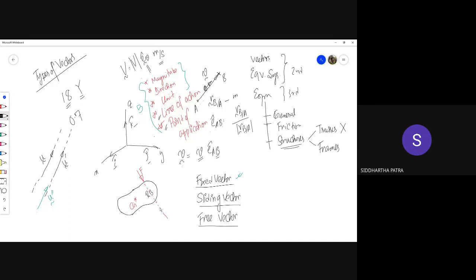So there would be an angular acceleration. So both linear and angular acceleration, and that would happen on the rigid body in the same way, instead of the force being applied on the line of action on the left side, if it were applied at the right side or the bottom side. So you can transfer a force anywhere along its line of action, and you can get the same result for a rigid body.